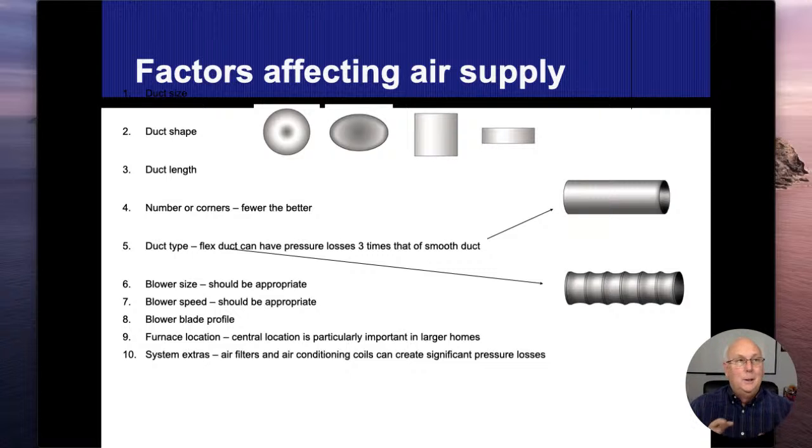We find those corrugated loop ones sometimes in attics. It's not very common in the Chicago area, but it's getting to be more and more common. So the rougher they are, the bigger the chance to reduce the airflow, the bigger the pipes they need to be. Hot air does move easier through ductwork than cold air.